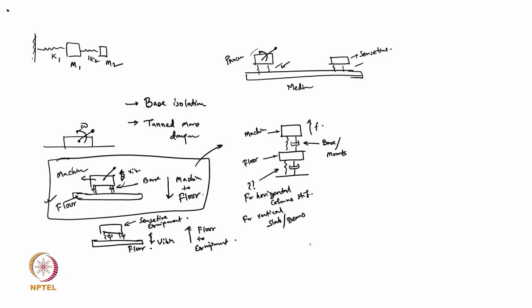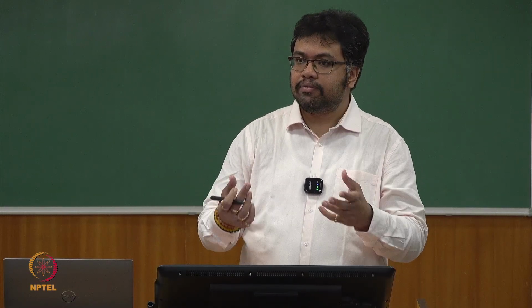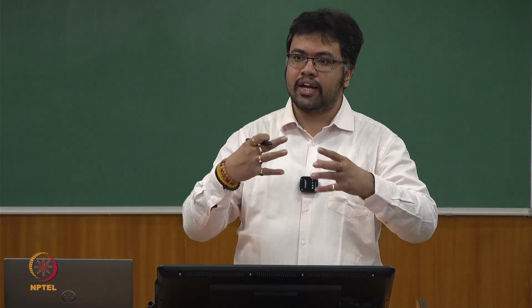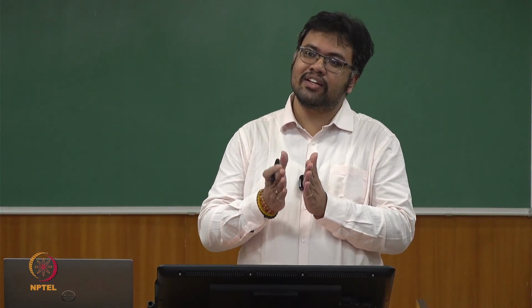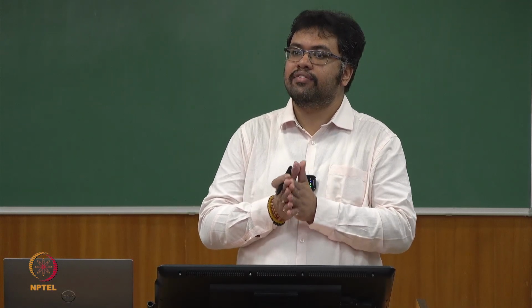Agreed? There are two types of damping generally present in this type. One is viscous damping, like air, or whatever the medium is; it may not be air, it may be something different. The second one is material damping. Suppose you take rubber or steel and apply shear; you will see that both do not have the same type of damping, because that depends on the interaction between the two layers of the medium, and how much energy is dissipated if there is some deformation.